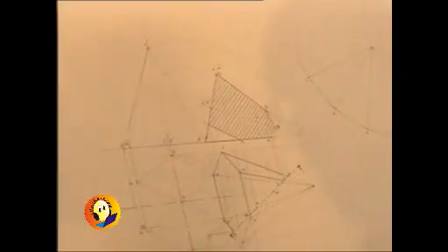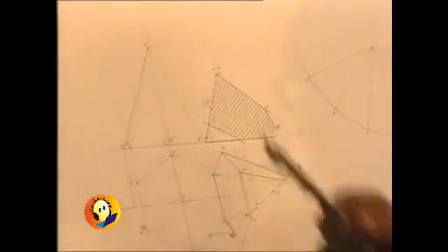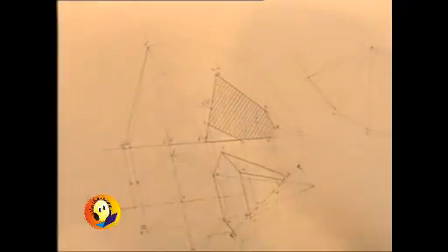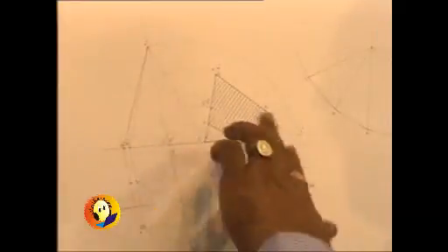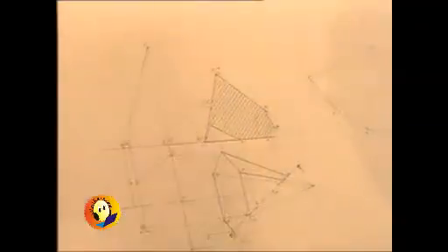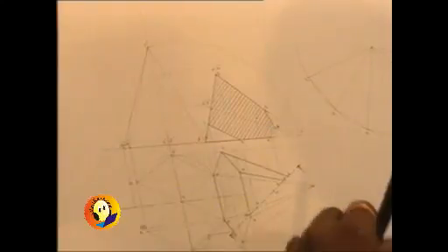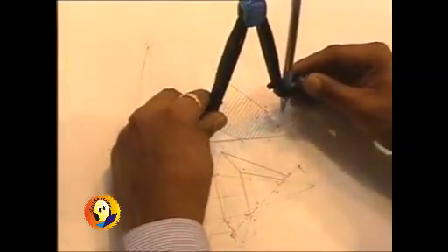Remaining points I will have to transfer to the respective generators, and then this is going to be rather a reverse process, so that I can take them to the true length. Other option is you will have to construct the true length over here and then proceed along with it. Even that choice can be exploited. In whatever way, whether I have rotated it, cut it, and then put it back and then transferred them to the true length, in whatever way we want to do it, it will be requiring the same amount of work.